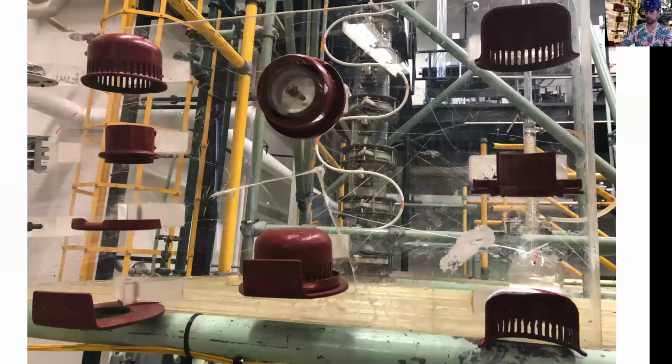In the trays at each stage, the type of plate that's being used uses bubble caps. When your air is coming out, it'll come up and over through here. Your liquid level is probably about right through here, right below this cap line. So any air or gas vapor coming out has to go up and out through there. You can see here the perforations. Here's another demonstration of it, coming out like that.